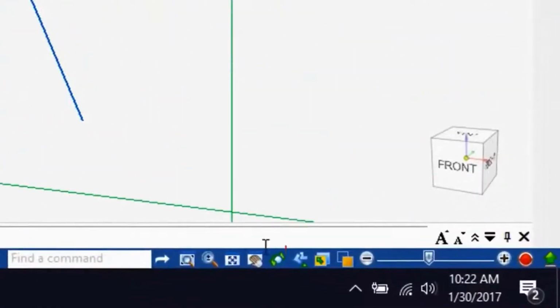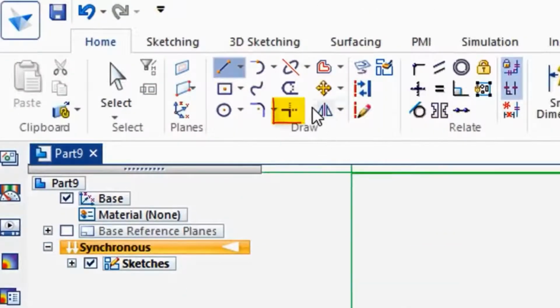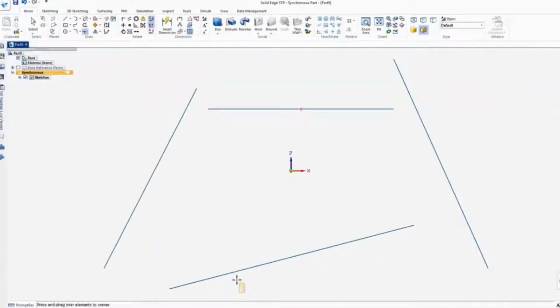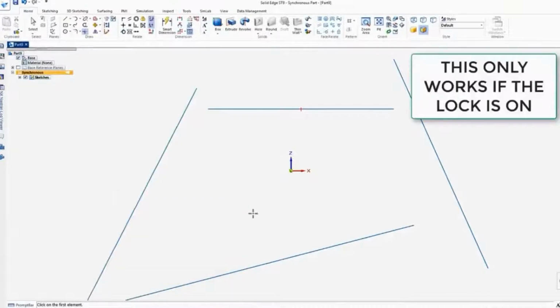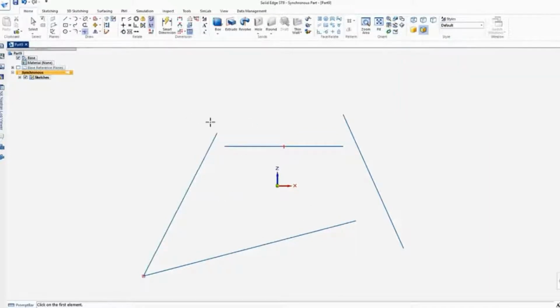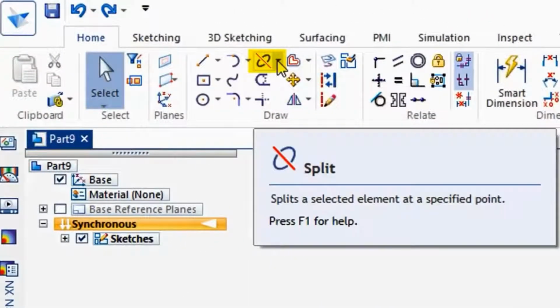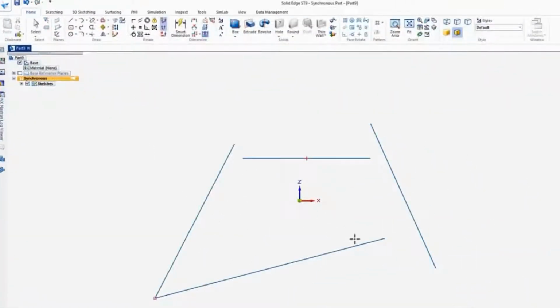Now I'm going to go down here to my sketch view, so I'm looking at that square on, and if I come up here to the trim corner, you'll see if I simply drag the cursor across there, it connects those lines. So again, to do that, I just sweep across the two and it connects it, the trim corner. You could also go up here to the split command, and if I pull down on the split command, there's an extend to next, and I just touch on the line and it extends it to the next. Whichever end I'm closer to, it extends that line.